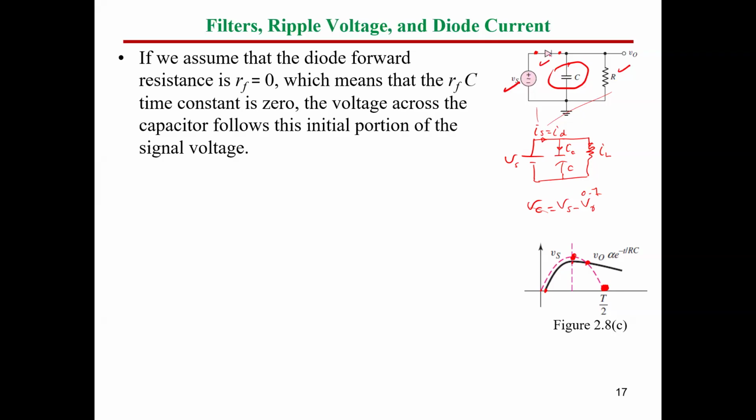Theoretically, the diode will be turned off if the current reaches 0. But let's assume now, according to the voltage waveform, the volt here is going to be equal, and this means the diode will be turned off and the capacitor will start discharging the stored energy in the connected resistor. So this is what's happening here, guys. We can assume that this is the waveform of the capacitor now.